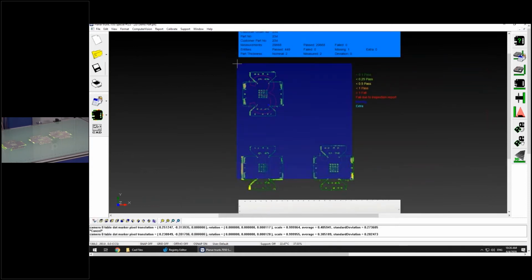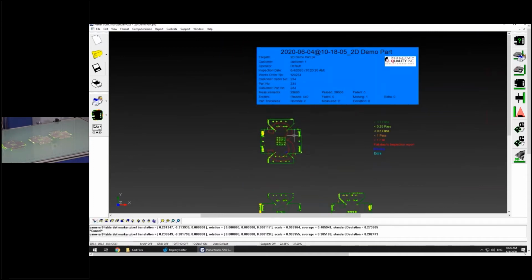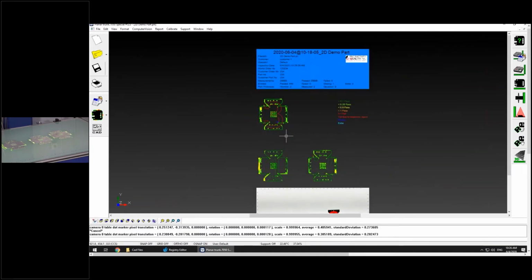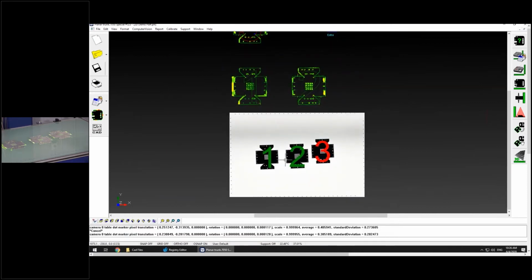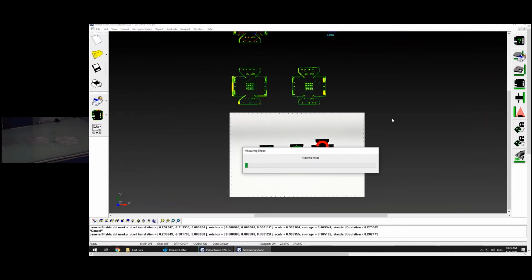Yeah, what they do here is however many parts you have, they just kind of put them out in the best grid possible. So in this case, the bottom left is 1, just like you normally would on your graph of your table. And here's my machine 0. So then they'll have 1, 2, 3, and if I would have put 4, 4 would go there. And if we had 5, it would do another row. So they're just trying to optimize the layout? Exactly. And actually how these machines measure the parts is from this side up: part 1, 2, 3. So I can make this inverse, and I can now make this one part 1 because that's nearest to the operator. So once you kind of learn that, you actually kind of know the idea behind the machine as well.